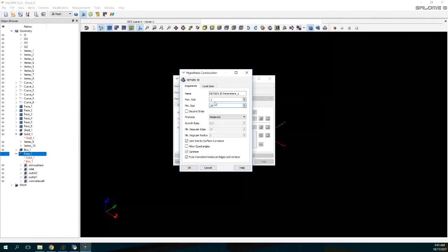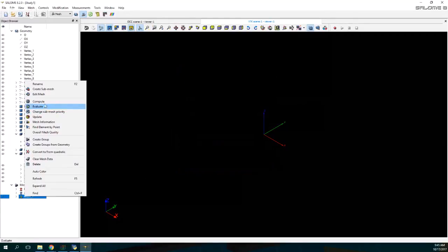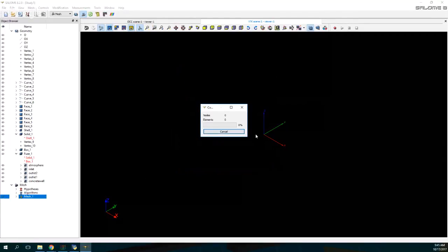I mean, the water intake that you are planning to simulate only has 1 meter of depth. So if you don't put an appropriate number of cells, you will have very low resolution of how water is going through the intake. Okay, then later on you can do some specific refinements that may be of much profit to run this model faster. But in this case, we are going to do a refinement for the whole project. Okay, so we create this. We say apply and close, and then we go to mesh, and then we say compute. Okay, this mesh is coarse.